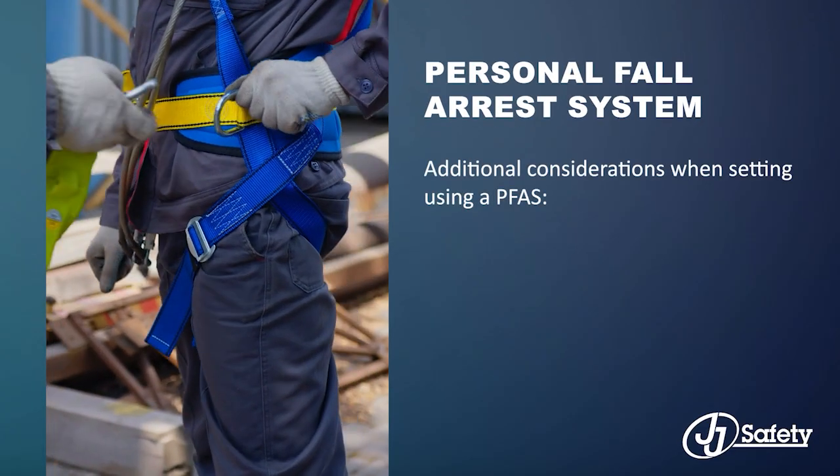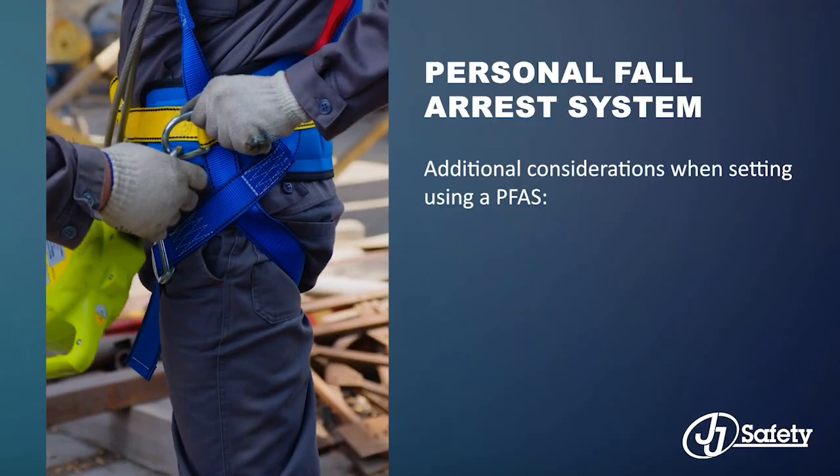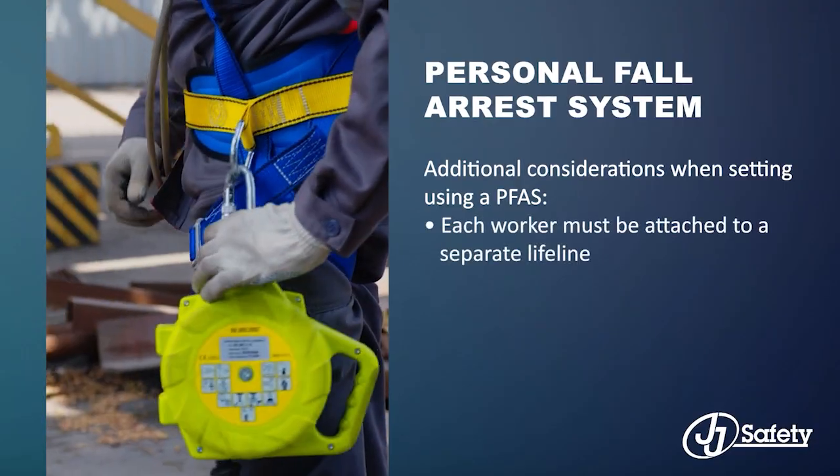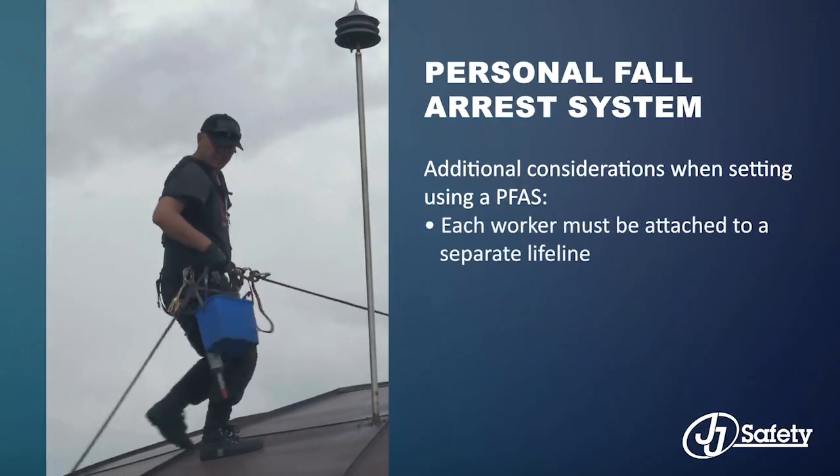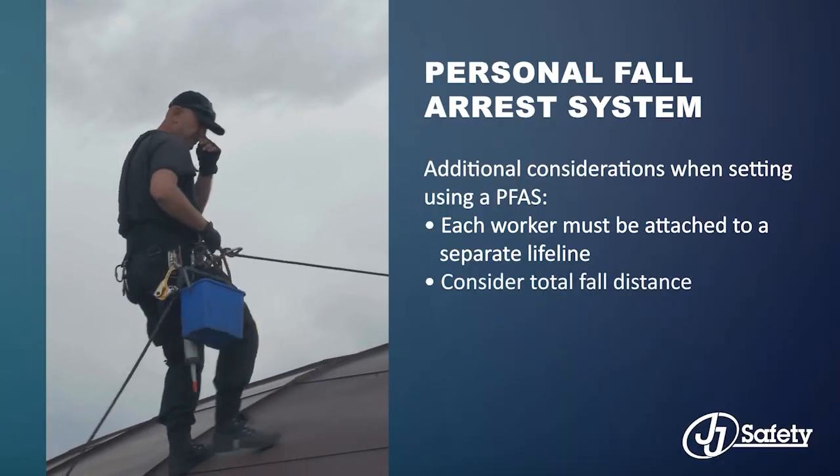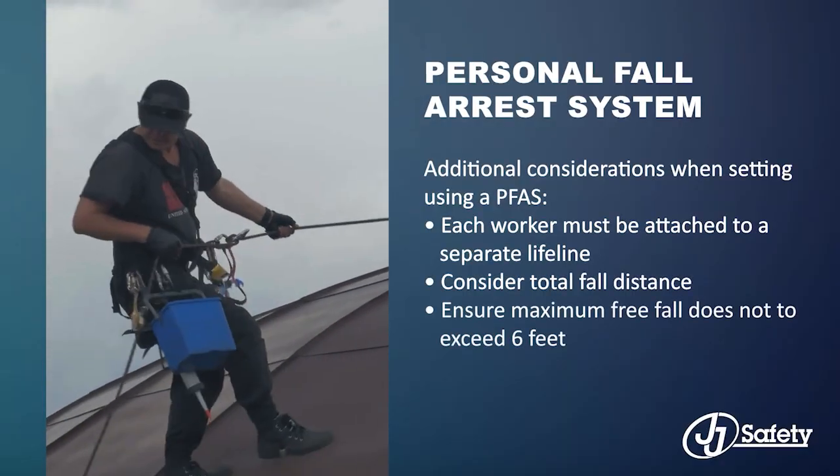Additional considerations when setting up a personal fall arrest system. Each worker must be attached to a separate lifeline. Consider total fall distance and ensure maximum free fall does not exceed 6 feet.